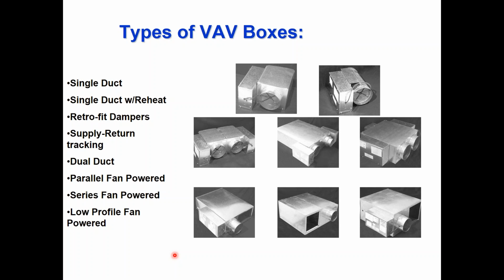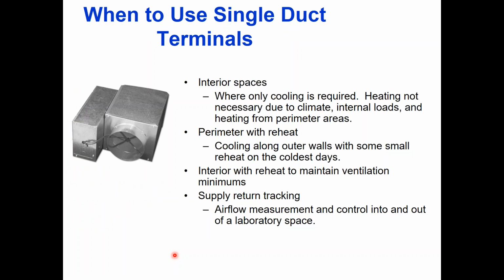The other common ones that you'll see a lot, well, single duct with reheat are both common, and then parallel fan powered and series fan powered. Those four are going to be the most common types that you'll see, but we'll touch on all the types. So these single duct boxes, just a regular traditional box. You can see this guy over here on the left is what he looks like. He's not super sexy.